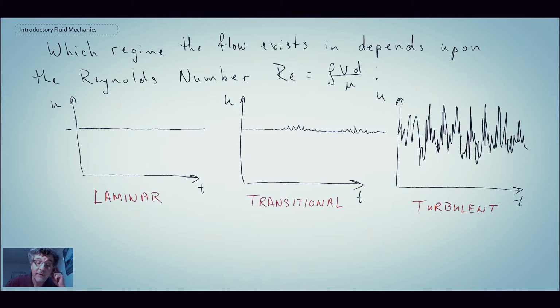And then the same with laminar. You can do power spectral analysis on that, and by looking at the power spectra plotted in certain ways versus wave number of the flow. I won't get into details with the wave number, but you would have a certain slope for laminar versus turbulent flow. So that would be what the signal would look like. But again, with turbulent flow, you are going to have some average values. You do have statistics with turbulent flow that enable you to determine things, and they will be stationary. They don't necessarily change with time unless your flow field is changing with time. So that is laminar and turbulent flows.